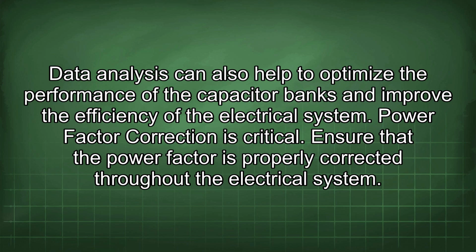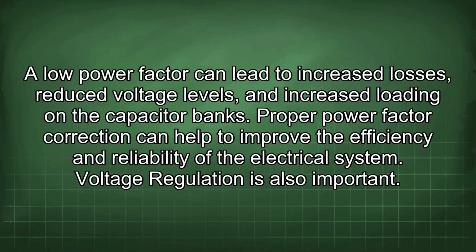Power factor correction is critical. Ensure that the power factor is properly corrected throughout the electrical system. A low power factor can lead to increased losses, reduced voltage levels, and increased loading on the capacitor banks. Proper power factor correction can help to improve the efficiency and reliability of the electrical system. Voltage regulation is also important.